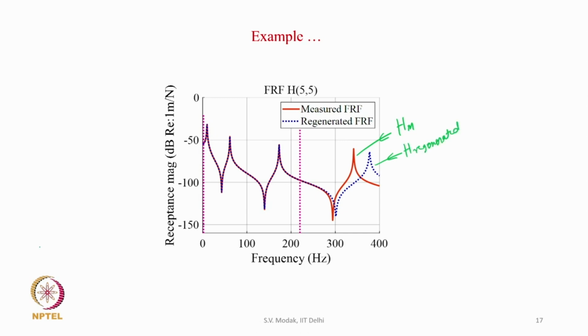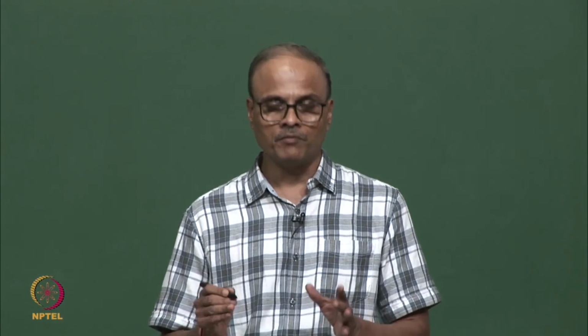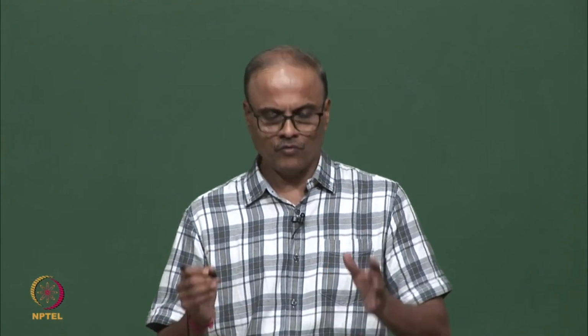So, we see that in the selected frequency band, the band in which the curve fitting was done, we are covering the first 3 modes. The fit is excellent, and therefore, the multi-degree of freedom curve fit using RFP is quite accurate, and it has been able to fit multiple modes and account for their contribution simultaneously.